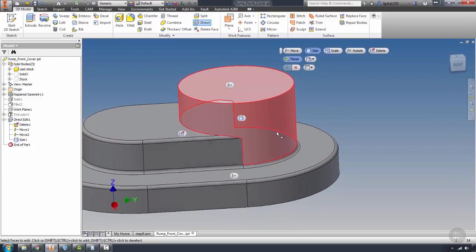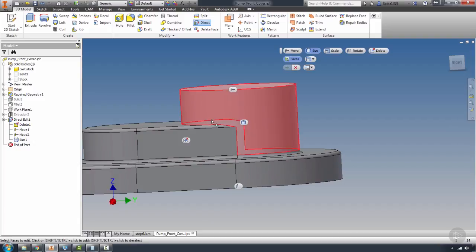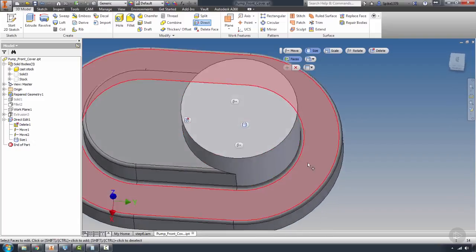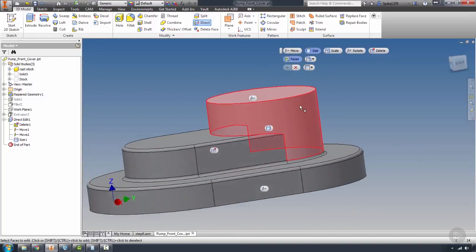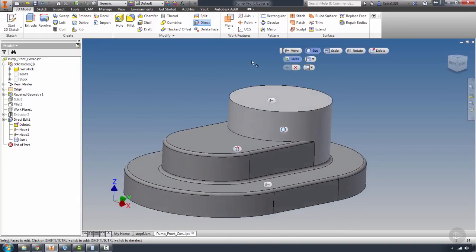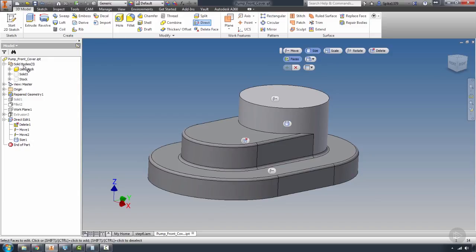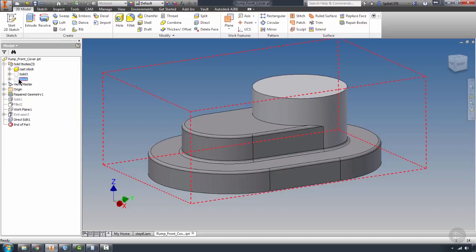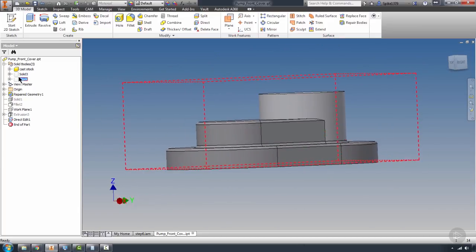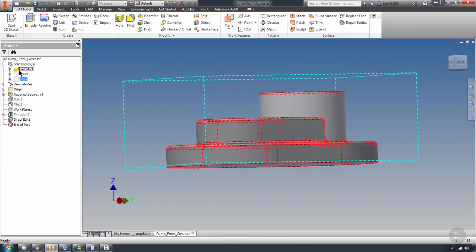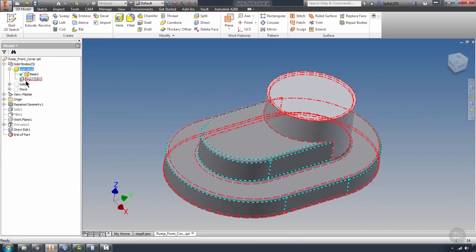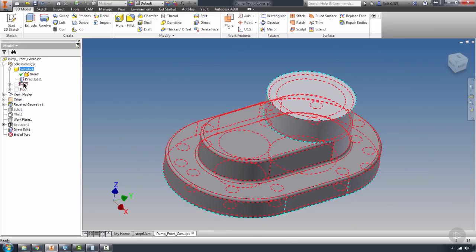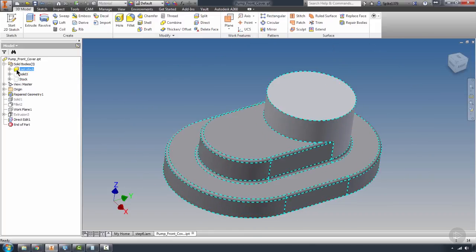Now we sacrifice that radius on the other side, but what we can do is machine that down on that entire face, blend it in, and then machine our threads accordingly. But now we have a direct edited solid cast stock to use within this part. We also have the original stock that we created, and we're going to keep that as well. But now we can choose how we want to machine this part based off of one individual part file, nesting all of the options internally into it.